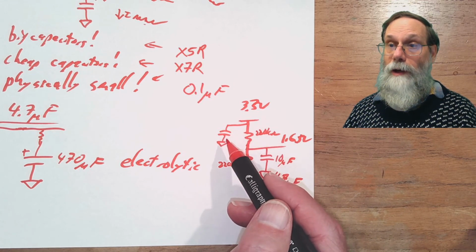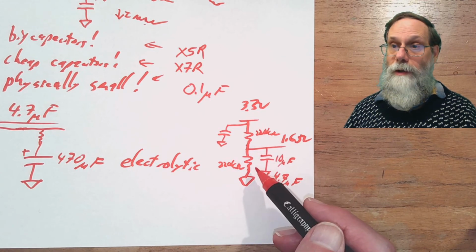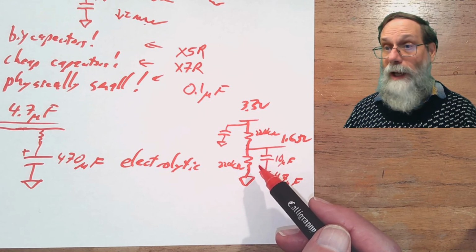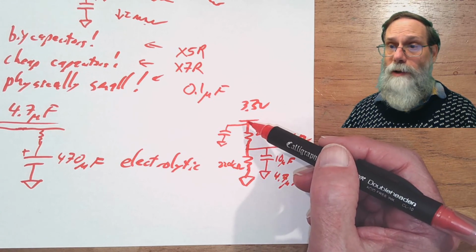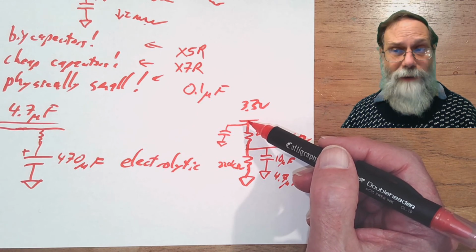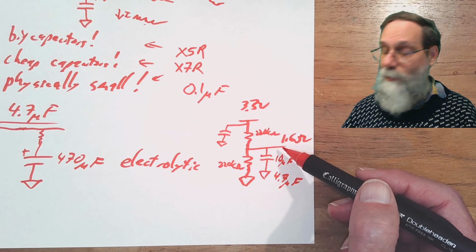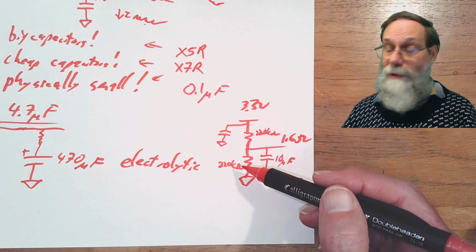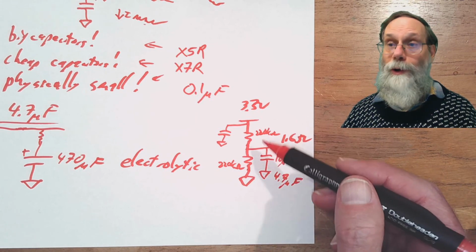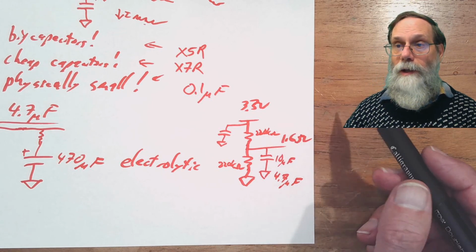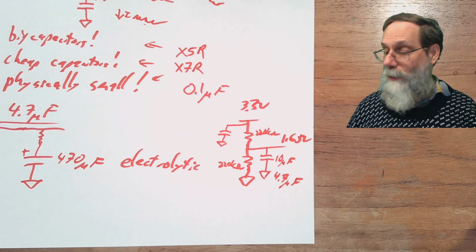and so even with a huge capacitor here, I'm not going to be seeing the same sort of low frequency filtering that I can get with a big capacitor and big resistors. And so if I'm trying to get rid of 60 hertz hum or something like that from my reference voltage, a bypass capacitor on the power supply is not going to do it for me. That'll get rid of very high frequency stuff, but it's not going to get rid of the low frequency stuff. To get rid of the low frequency noise as well, then I need to have big resistors. And notice I can't take current from this thing because there's almost no current available. If I take any current, the voltage will drop. So that's got to be something where I need the voltage, but I don't need to take current from it.